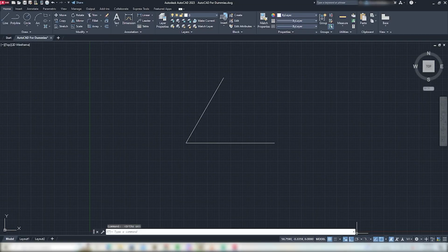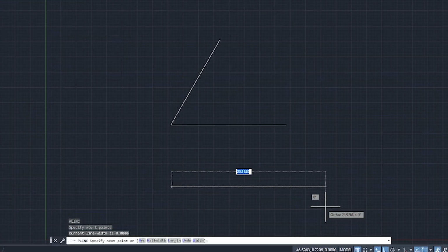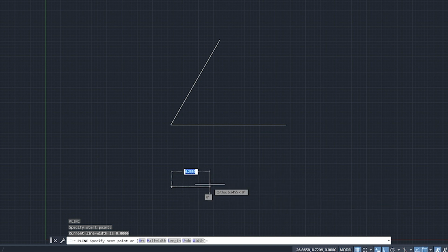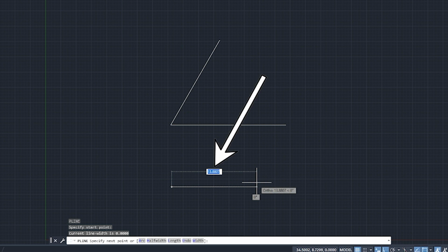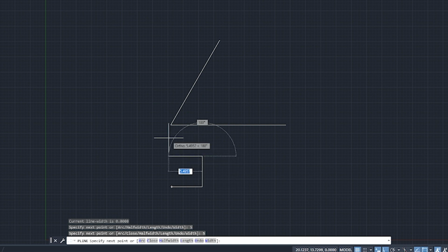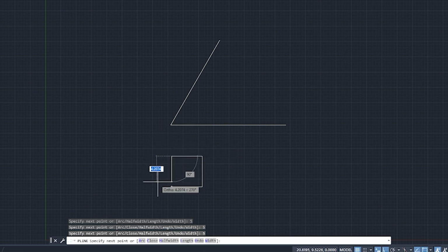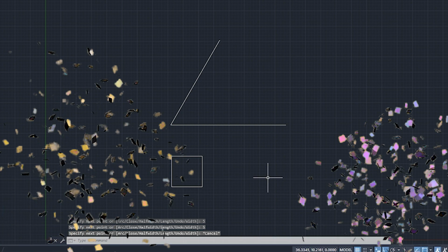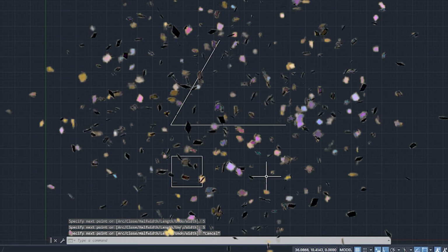So what we're going to do is we're going to click that on, and I'm going to show you by hitting a polyline again. But now you're going to see there's no green line, but I'm just going at a 0 degree in the horizontal and a 90 in the vertical. But it gives me that dialog box to also go that same distance I want to go. So this time I'm going to go 5. I'm going to go up 5. I'm going to go to the left 5. And then I'm going to go back down 5. Completing my rectangle a little bit faster actually than Polar Tracker.